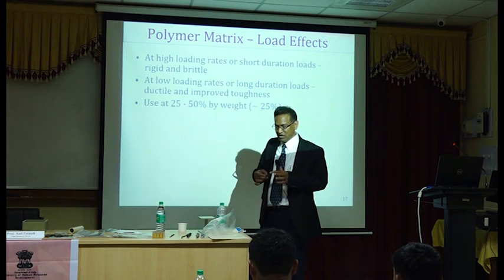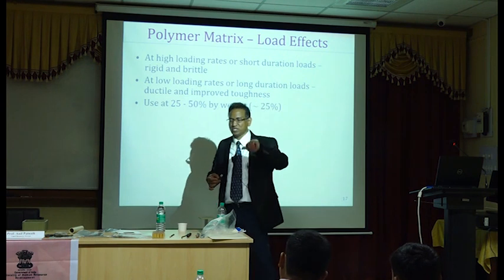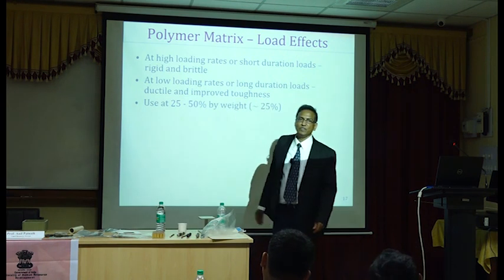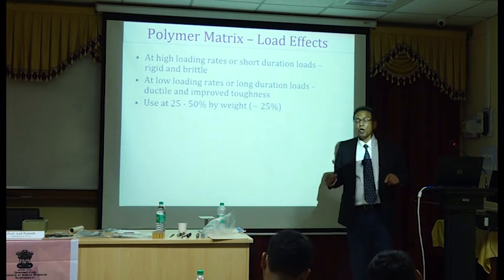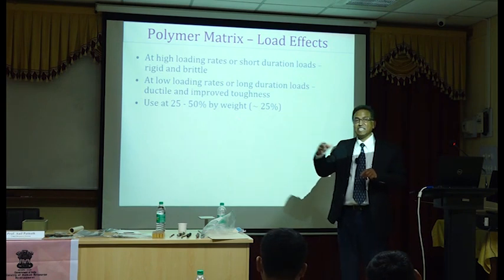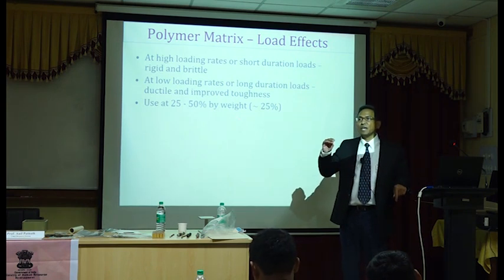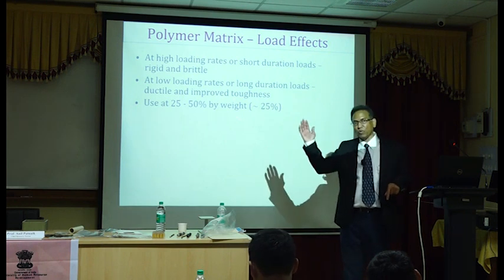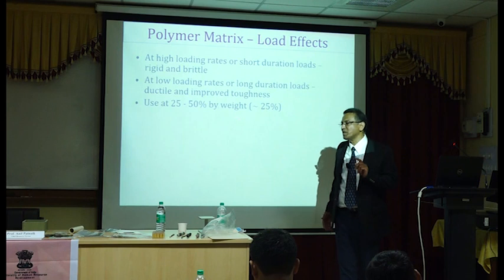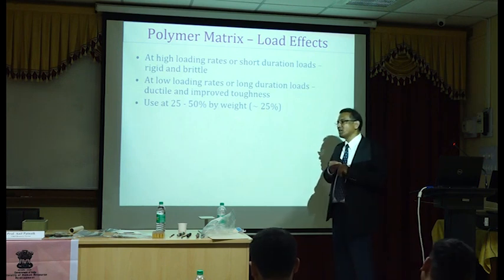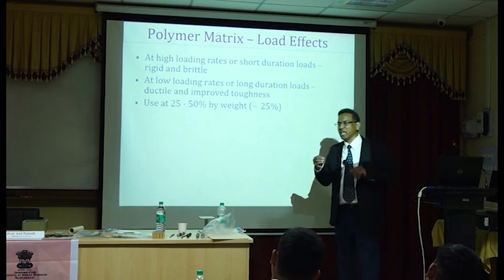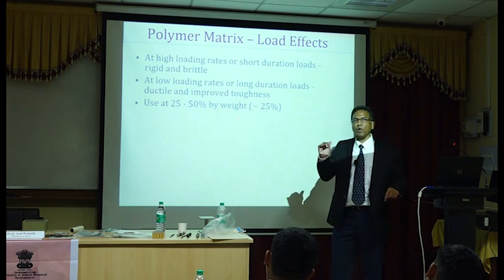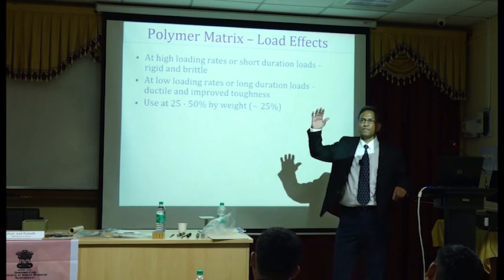More the fiber, better or worse? For strength, it's always better. But the matrix will not wet the fiber over the entire surface, which is a problem. So if you want to have efficient load transfer, it's better to keep the fiber volume fraction not that high.